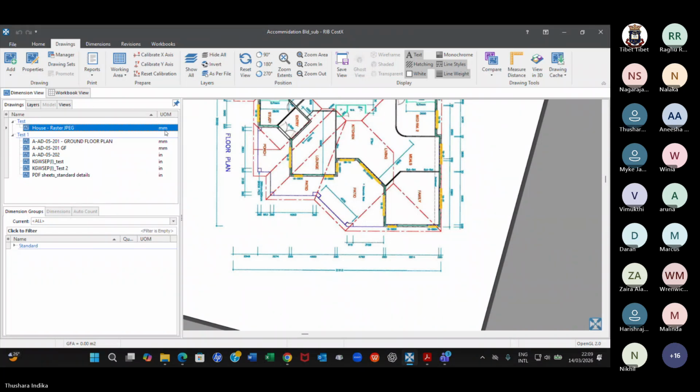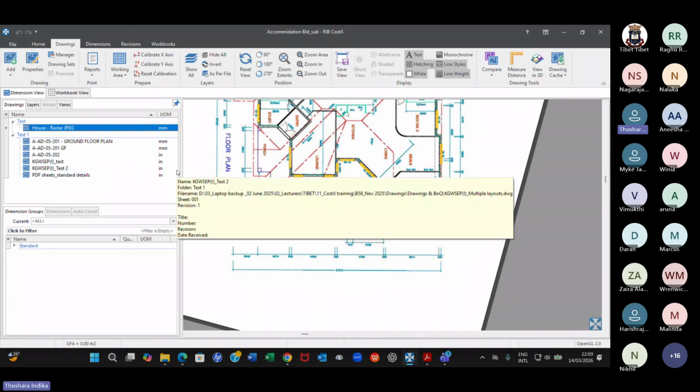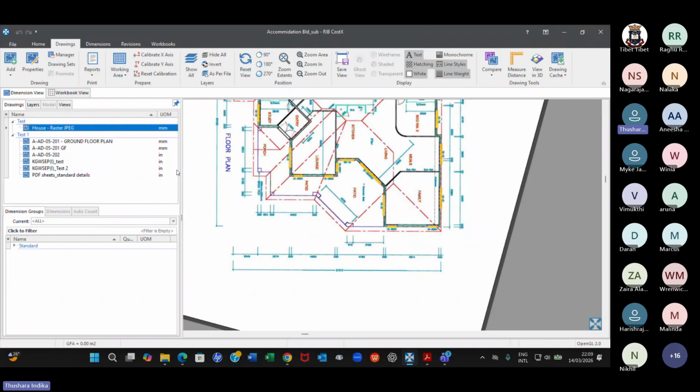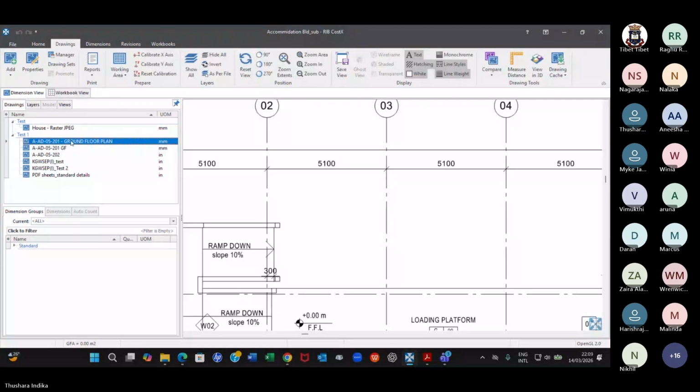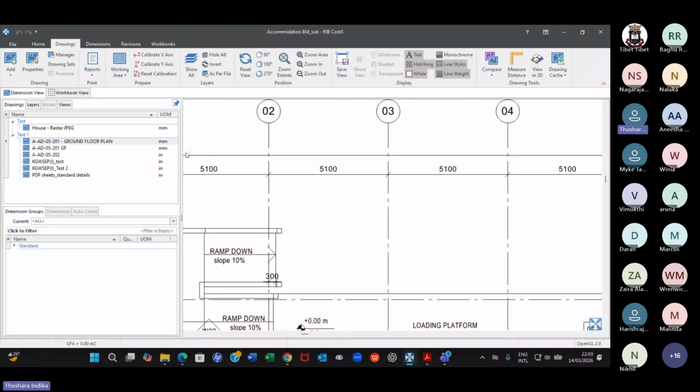Earlier it was inch, which is not correct because our measurement was not imperial, our measurement is SI. So it has to be project meters, drawing millimeter. If it is inches and feet, then project feet, drawing inches. Are you getting me? All right. Now I go to, sorry, PDF. Yeah, now I'm ready.